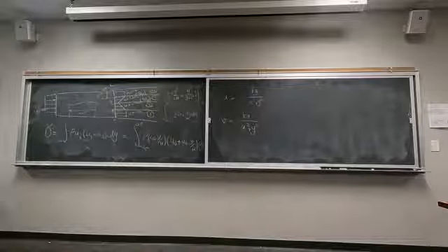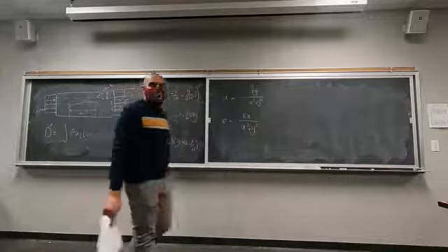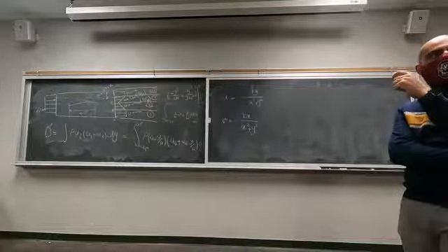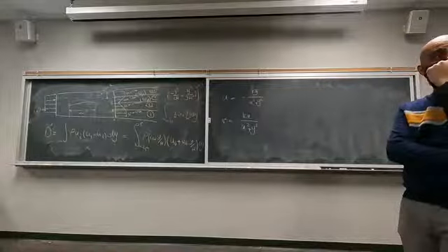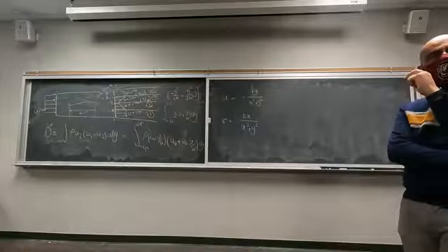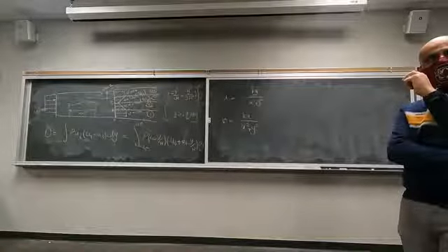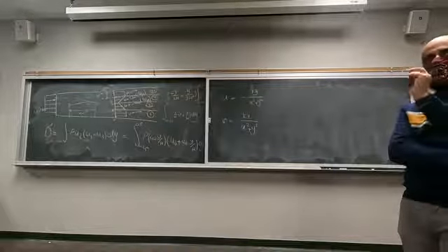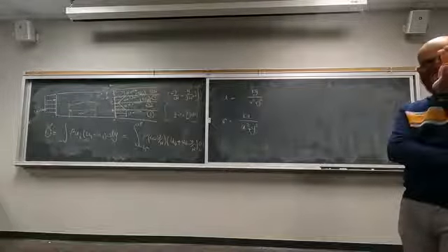The first thing you need to know is what is the mass conservation for an incompressible flow? Anyone? We talked about it, right, in the beginning of the class. Conservation of mass for an incompressible flow. Okay, so we are dealing with an incompressible equation. How can you simplify that? Exactly, and you can take all the rho out of the differential, take it to the other side.